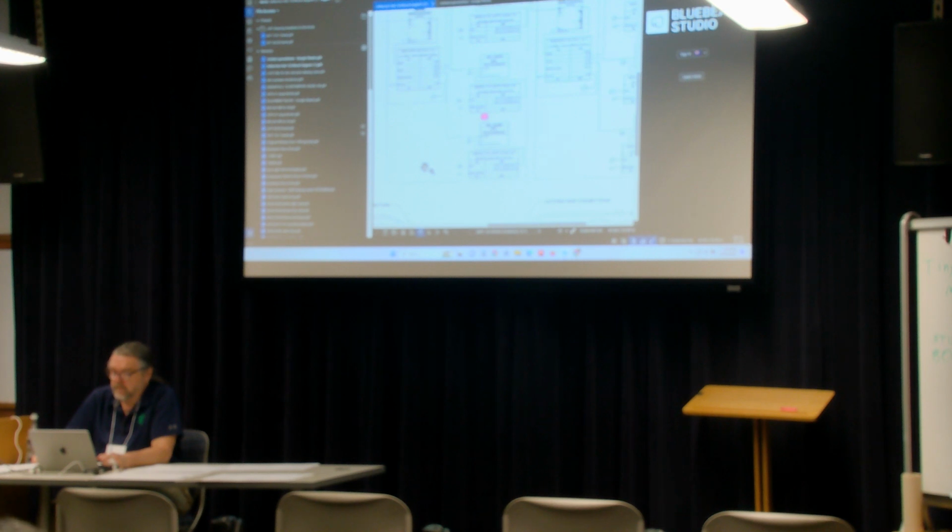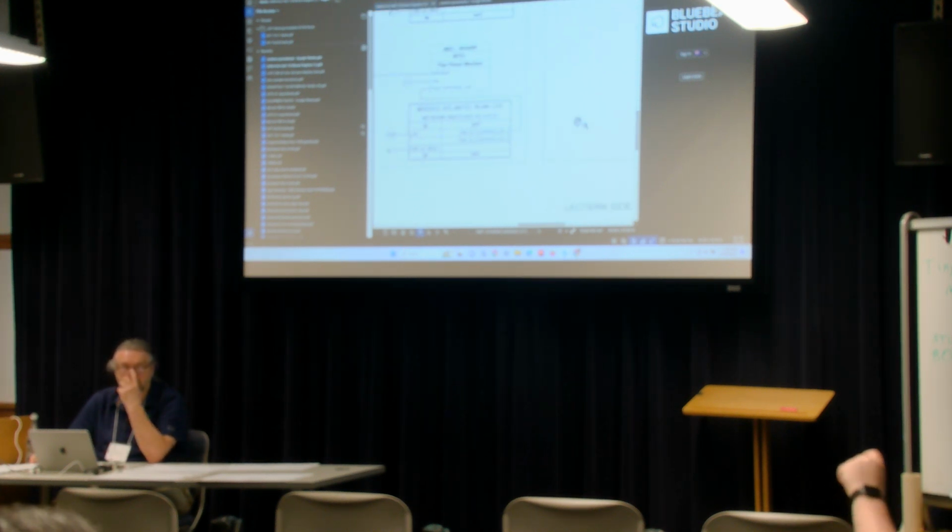We have a homegrown system that we created, that's similar to D-Tools. One thing I do like about ours is we color coded a little bit. So all the video cables are blue on the drawing, all the audio is green, and all the control cables, which more and more things are just control cables these days, are red. And then actually the title part of each block, we color code those to mean some things too.